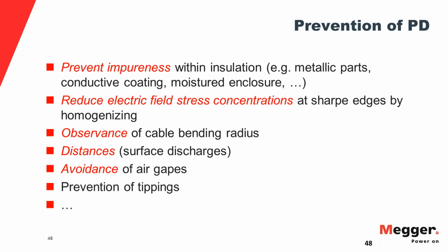Observe the bending radius. Classic mistake. They bend the cable too much, and on one side it's compressed, on the other one it's stretched. You get voids. All of these things. Just do a proper installation, and you will have a very nice PD-free life.